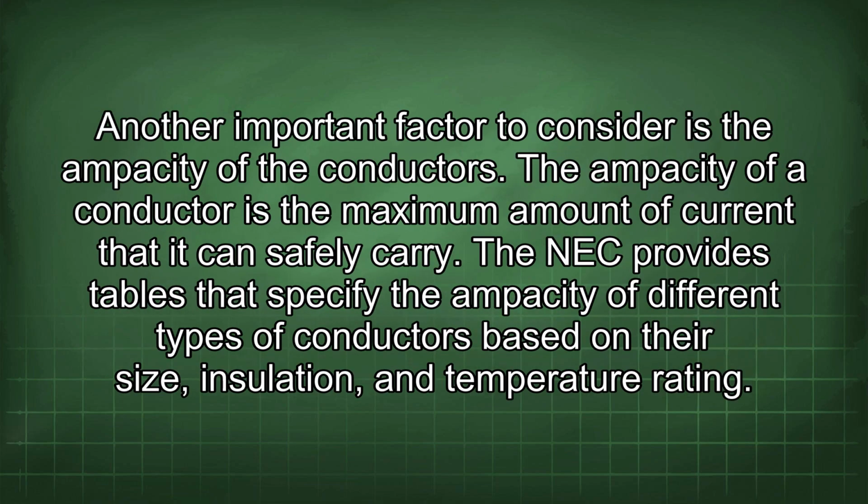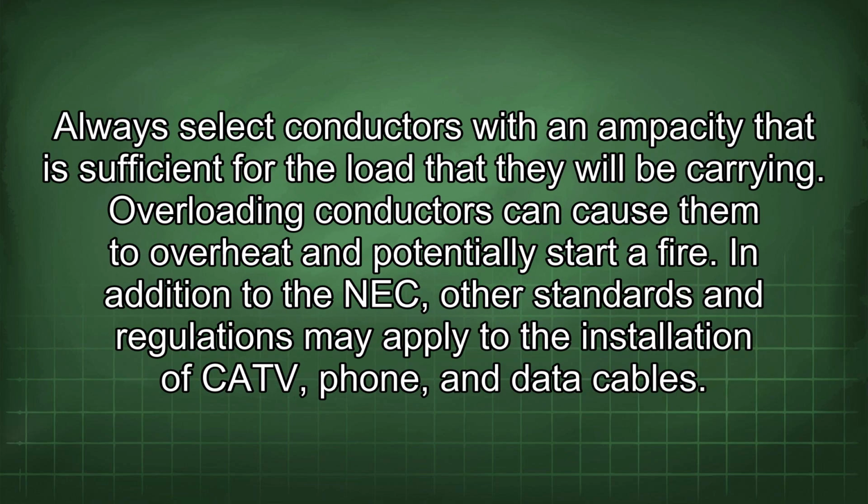Another important factor to consider is the ampacity of the conductors. The ampacity of a conductor is the maximum amount of current that it can safely carry. The NEC provides tables that specify the ampacity of different types of conductors based on their size, insulation, and temperature rating. Always select conductors with an ampacity that is sufficient for the load that they will be carrying. Overloading conductors can cause them to overheat and potentially start a fire.